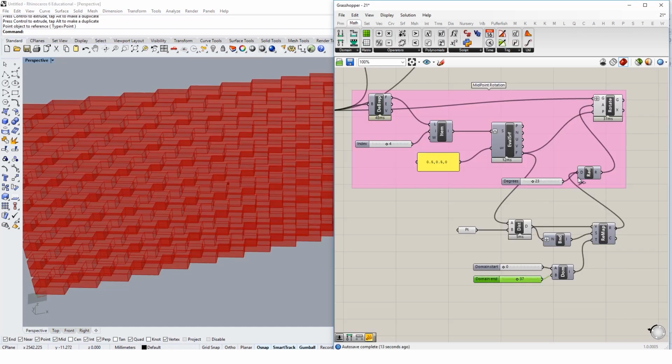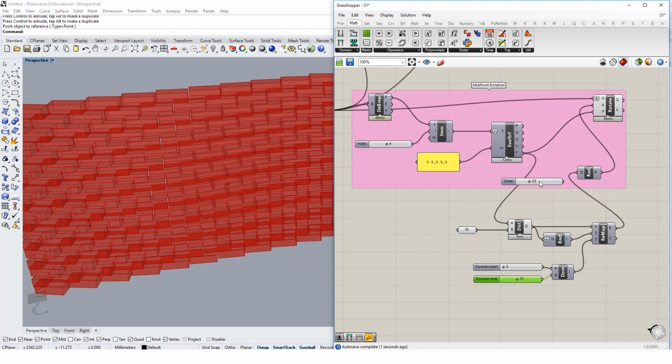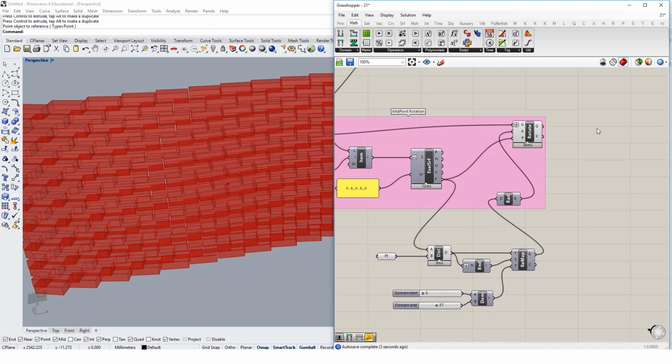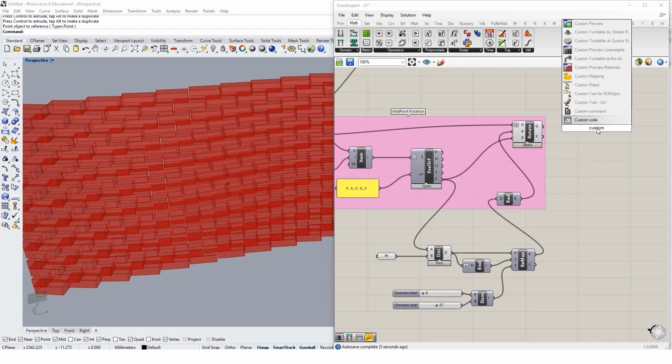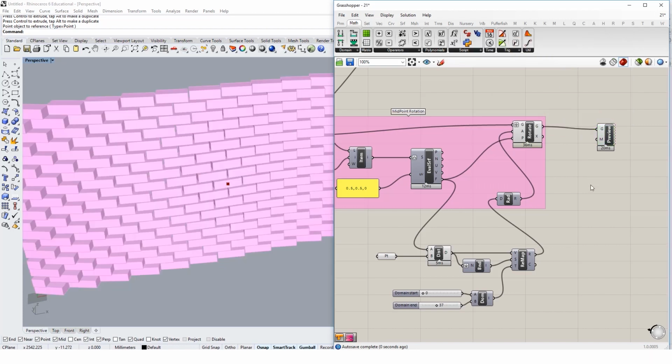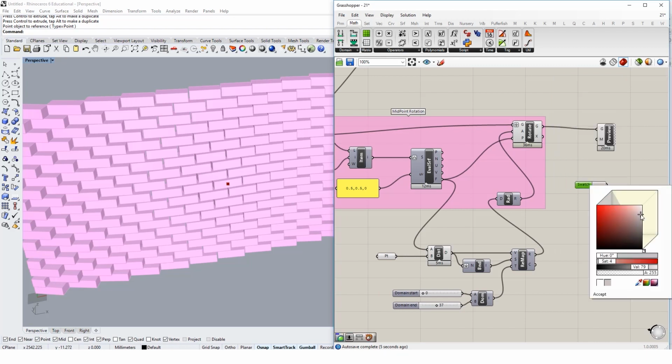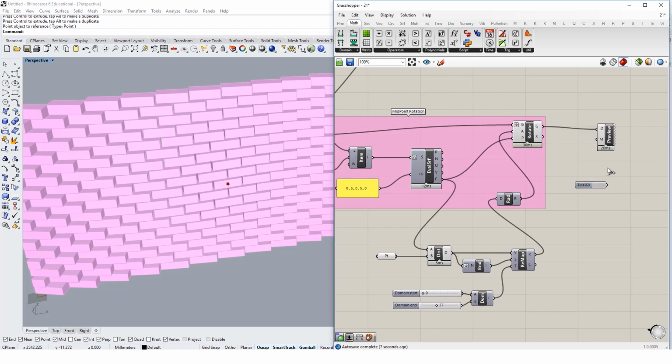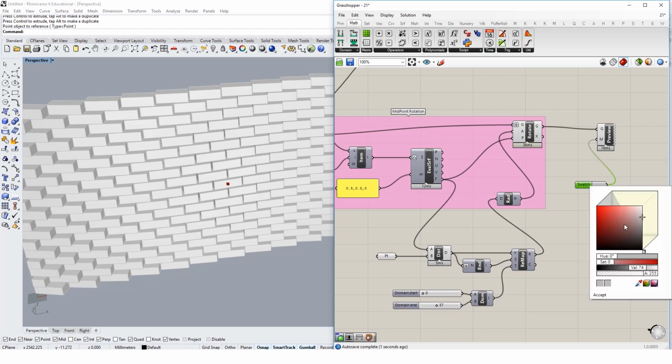Once we have created our first brick wall, we can then extend this logic a little bit further by adding attractor points to recreate a precedent study, the Winery Gantenbein project by Gramazio Kohler. This project uses robotic fabrication to create a brick wall facade with rotating bricks that respond to a series of attractors and images. We will recreate this in Grasshopper by parametrically rotating individual bricks gradually based on their distance to an attractor point.